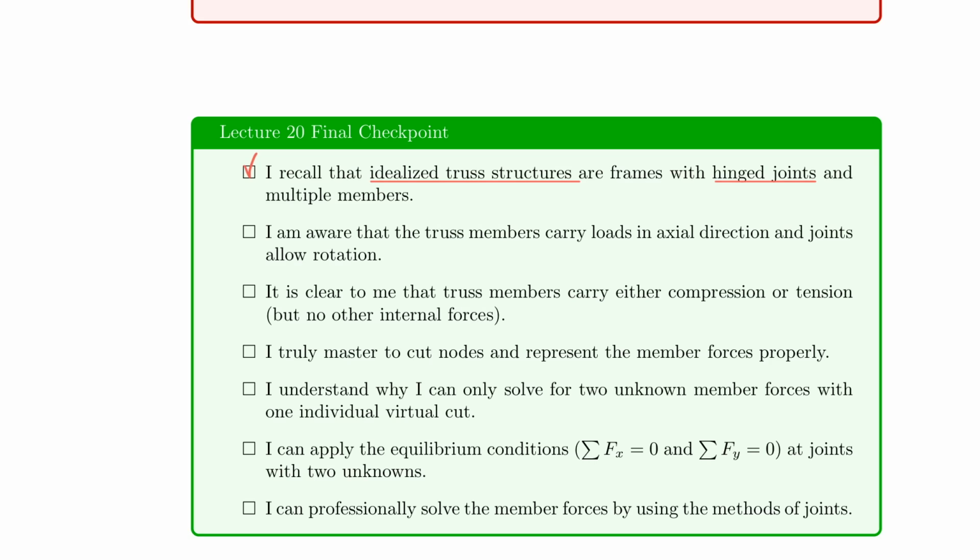I also know that only axial loads are really carried here, right? So axial loads is very important because that prevents shear forces from occurring and that also prevents moments from occurring. So therefore we're dealing only with normal forces, but we just call them axial forces in this case. And because we're dealing with axial forces, we can only deal with compression and tension in the members. So that needs to be clear as well. So please do not start to calculate moments or shear forces or anything similar to that.